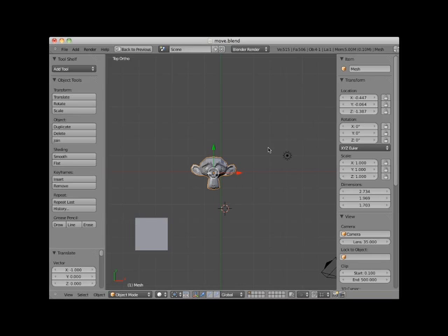Another method to translate an object in Blender, constrained to the object's X, Y, or Z axis, is to use the Location Control Panel on the right 3D Viewport Control Panel. Here I will select the cube object. Clicking on the arrow control to the right of the X location, I can move the object 0.1 Blender unit each click.